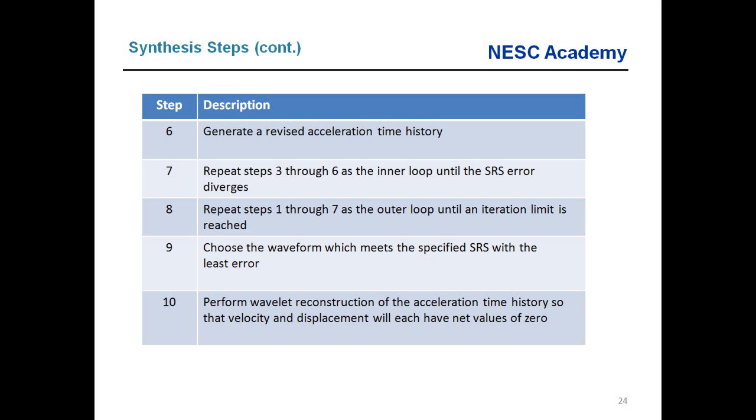And when we do this type of base input analysis, we're not interested in the absolute displacement. What we're really interested in is the relative displacement between two points, or between two degrees of freedom. And it's that relative displacement that becomes important because strain is proportional to relative displacement, and then stress is proportional to strain. So for our stress analysis, we want to know what the relative displacement is.